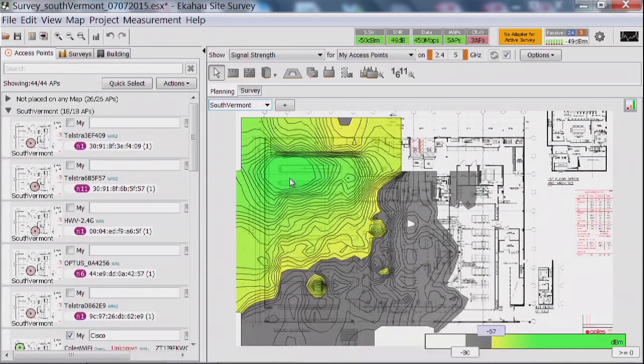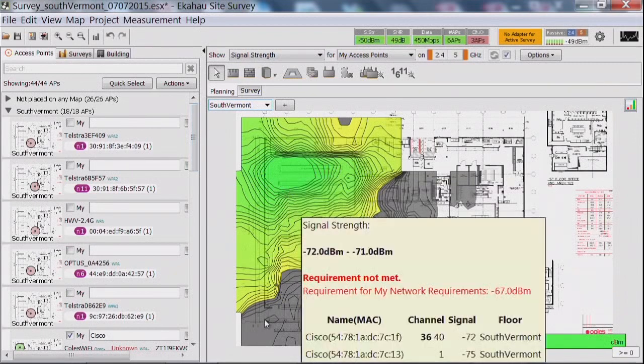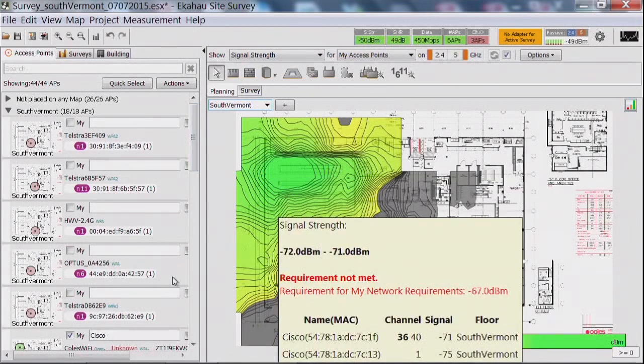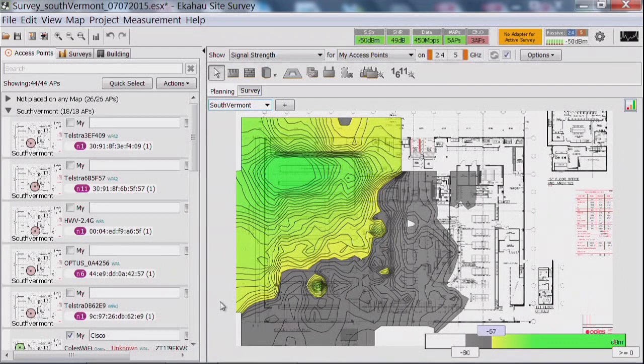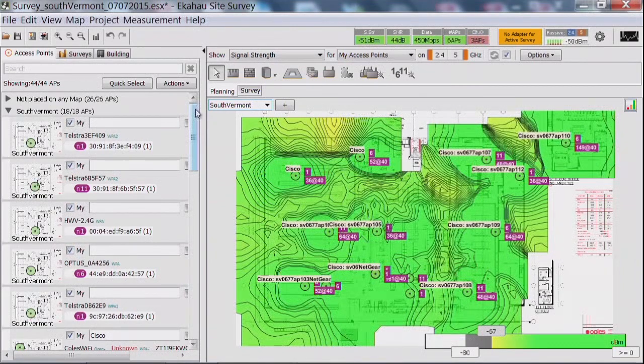Of course, you would do it for this access point, you would save your project, then take the AP, move it around, then do it again for the next AP, and you would accumulate the access points one after the other. So in the end, you would see the coverage for all the access points pretty much as if they had been deployed and you were doing a passive site survey on the resulting coverage. And that's how you get this result.